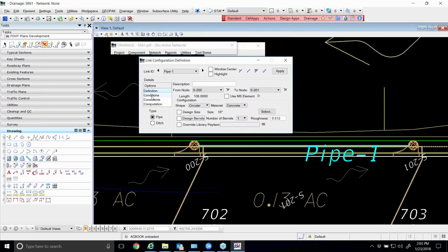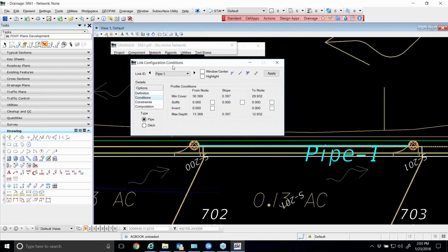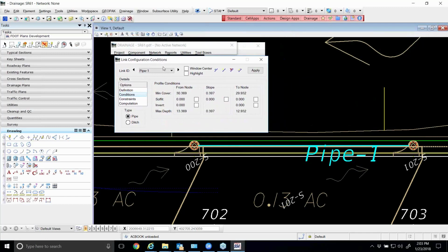If we are plugging this in off of a spreadsheet or some type of tab sheet, we do still need to fill out the correct elevations because this is going to get drawn in a profile view and a cross-section view. So you'll see here in the middle of page 512, step number 12, we have an invert here we're going to check on. So that's at the S200 of 32.9.